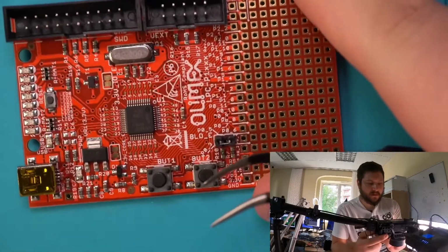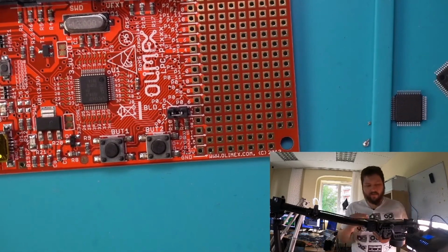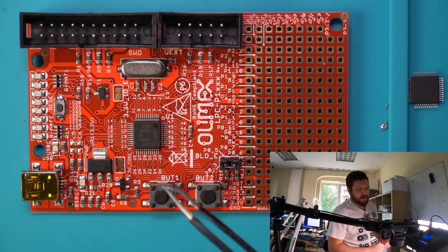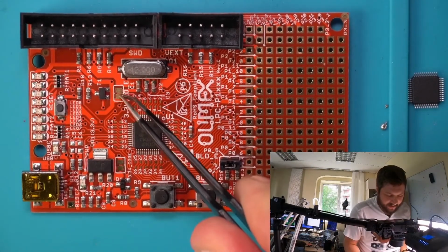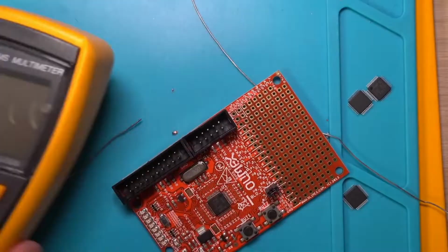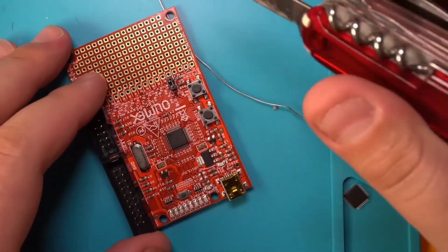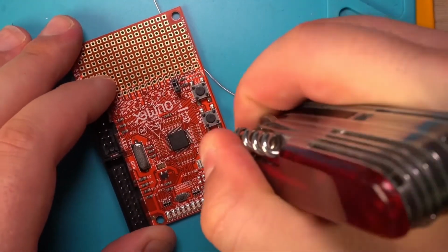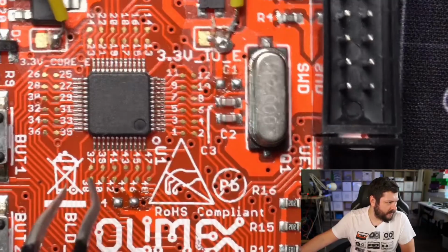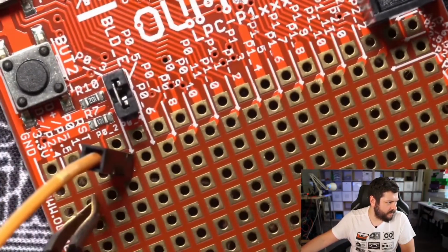They have these pads, and these are shunt pads. They're there so that we can sever them, put a resistor there, and then measure the current that goes through the system. If I cut through here, I will have separated the chip from the power supply and everything else on the board. So now let's sever that connection. I'm literally just going to take the knife, and people ask me how do I know that the connection's gone? And it's like, go until you hear a crunch. So I heard a crunch. I heard another crunch. I also removed a capacitor here, and I've permanently soldered one in.